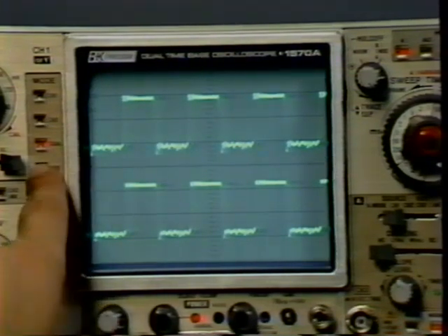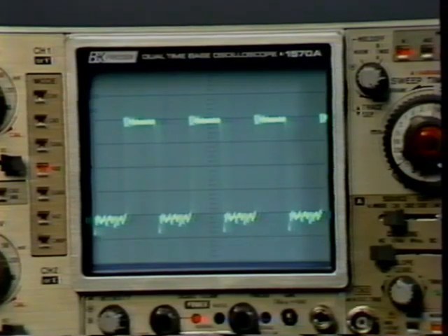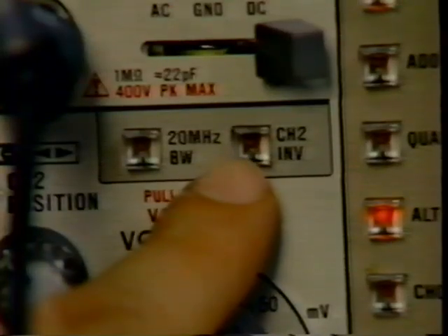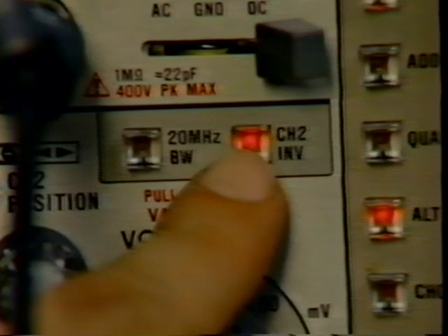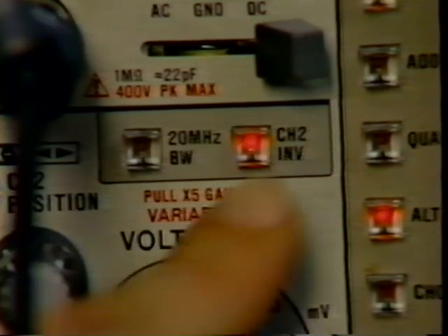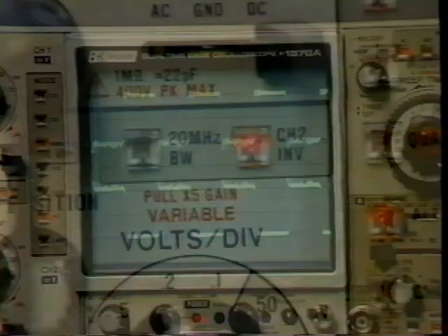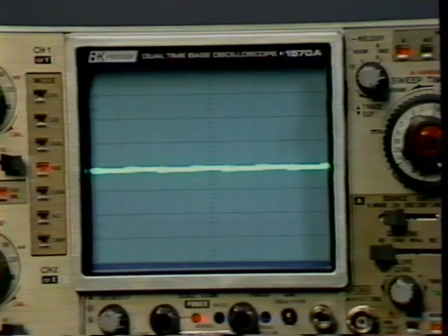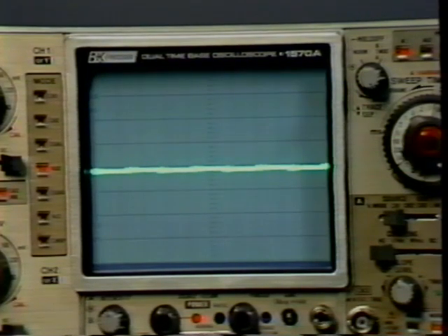This option displays the sum of the two inputs at any given time. If we add two identical signals, the display will show a wave with double the amplitude of either. Many scopes have an invert option on the second channel input. This allows us to amplify the difference in two signals. If we add two signals that are exactly opposite, a flat line will result.